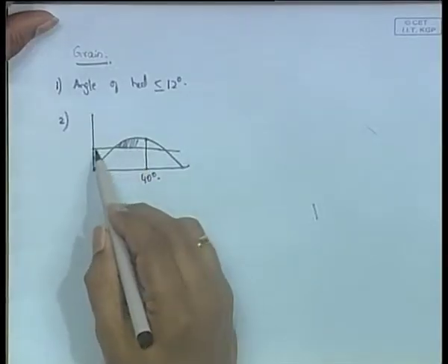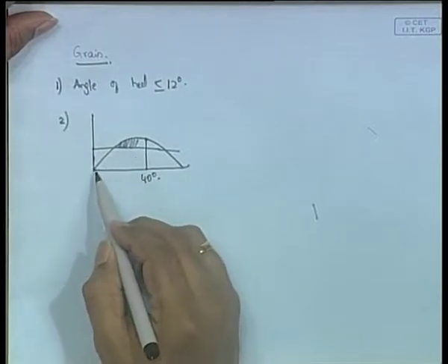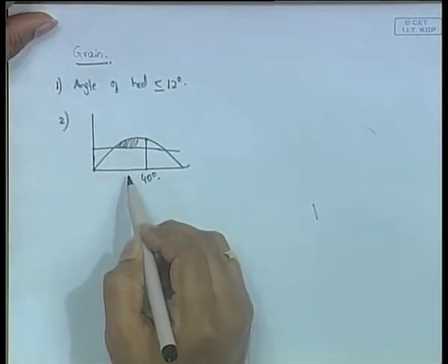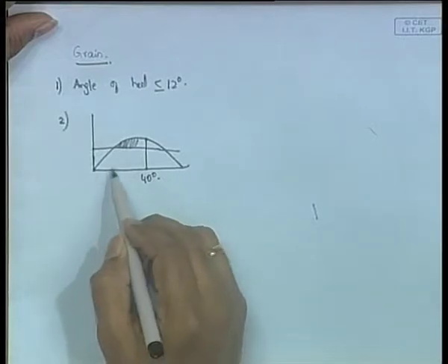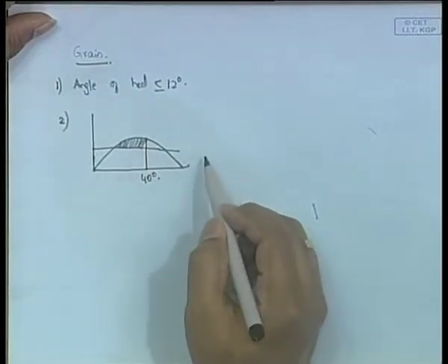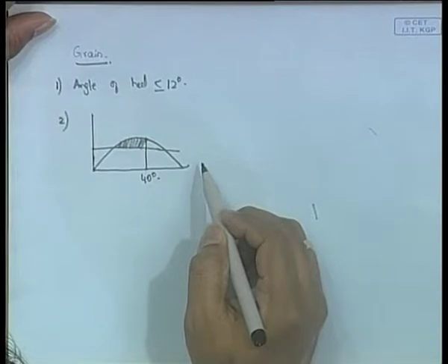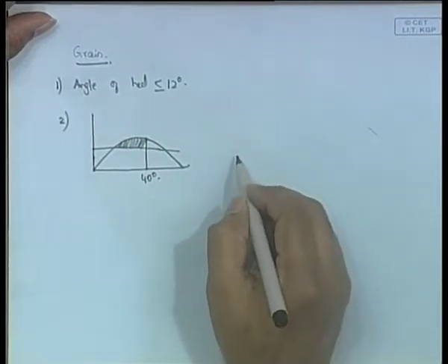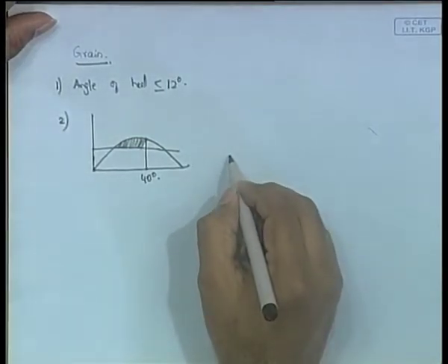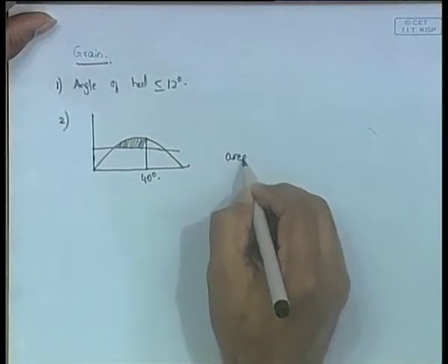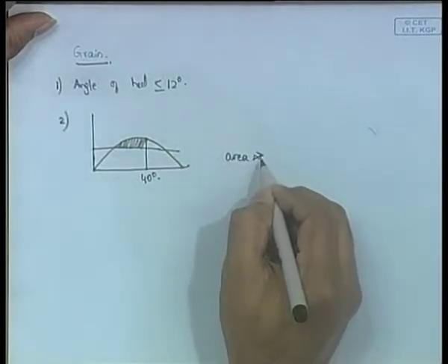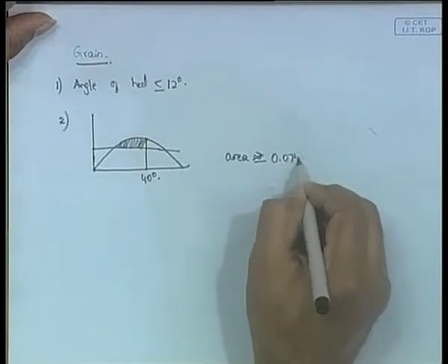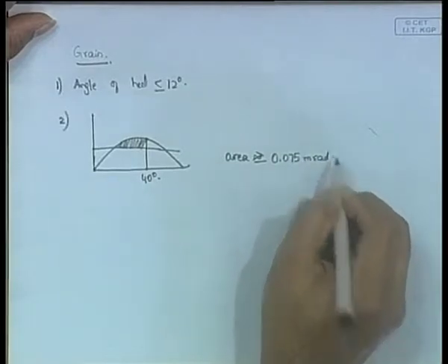So, the area in the GZ curve between the righting arm and the heeling arm, between the angle of 0 degrees and 40 degrees or the angle of flooding if it occurs before, should be at least 0.075 meter radians, or greater than or equal to 0.075 meter radians.